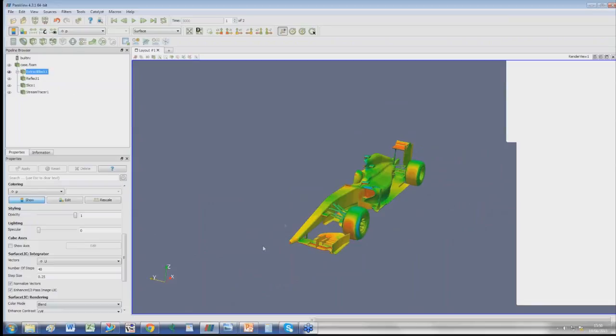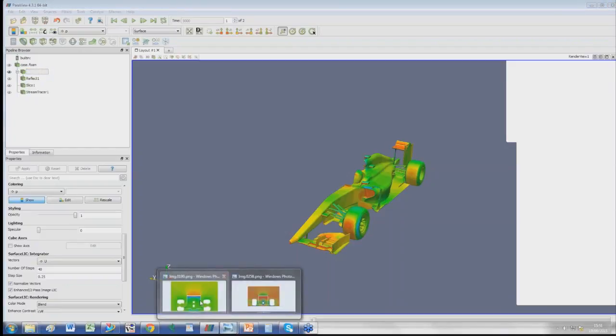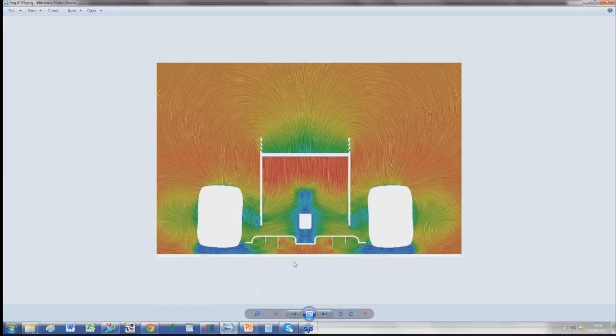Okay. So we've put a wall in the center of the car that would be what we call a slippy wall. So it's effectively simulating a symmetry of the flow. And so effectively we just create a symmetry to see these pictures, which means the flow is symmetrical in this case. We can also simulate full cars, and we've done that obviously in the past, and we actually normally do full cars most of the time when we want to simulate a steer or a car in cornering, but not in this case.